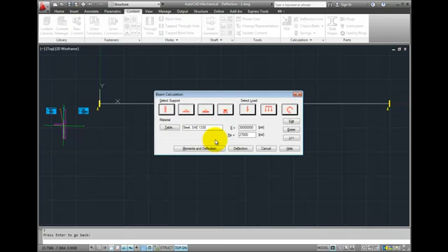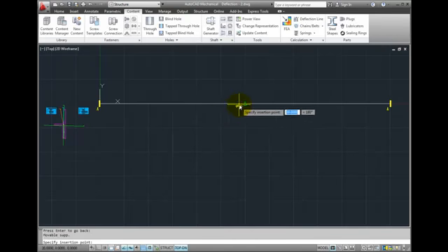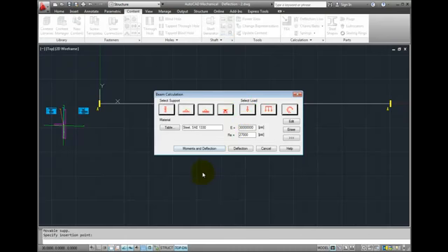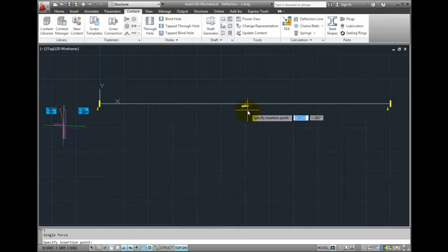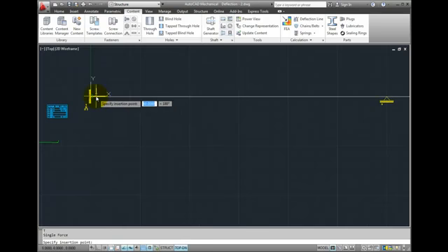And now I'll place a floating support in the middle. This is a complex support situation. It can be solved through classical formulas, but it's going to be easier to use Mechanical's tools. Now I'll apply some loads. Let's start with a point load. Place a point load approximately 18 inches from the left.